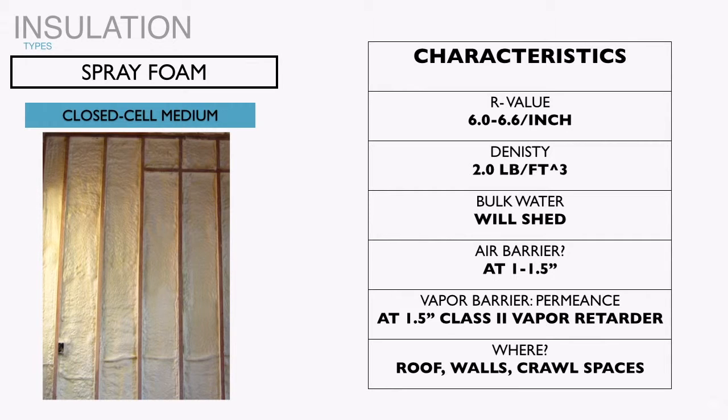In our climate zone, we generally recommend open-celled spray foam. Again, unless we have studied our building assembly and we understand our moisture sources, whether interior or exteriorly generated, and can effectively control them, before we would recommend closed-celled spray foam in one of our assemblies in a hot, humid climate. Now, none of this holds true for dry climates.